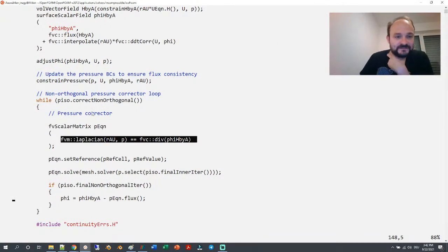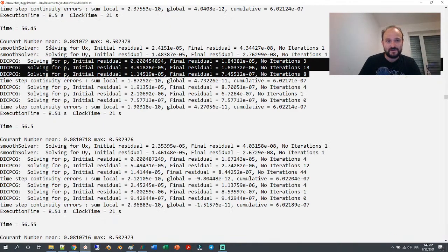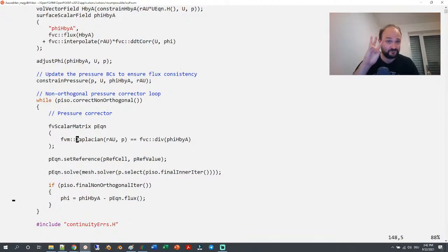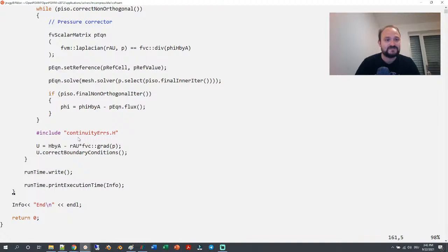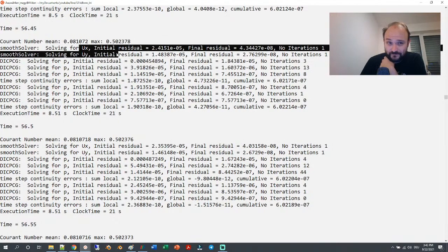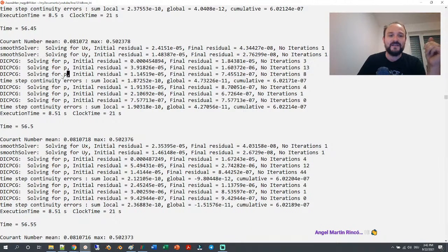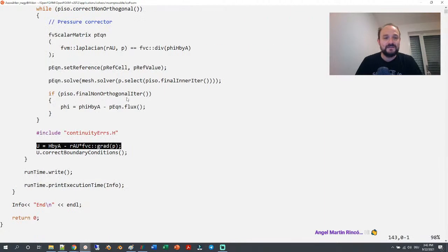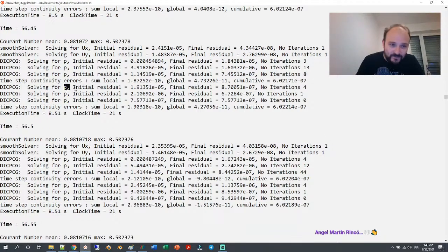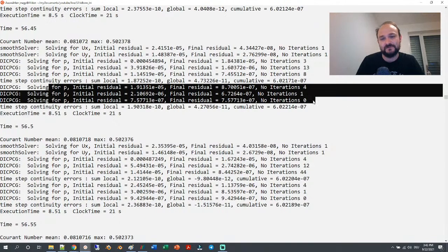But the difference is that we solve with the Navier-Stokes equations, then we solve these pressure equations 3 times, and then once we solve this, we calculate the velocity explicitly with the updated velocity. So we solve the Navier-Stokes equation, we have an updated velocity. Then we solve the pressure equation 3 times with this updated velocity. Then after the 3rd time, we explicitly calculate the velocity without solving any partial differential equations. And then we go with the updated velocity again 3 times into the pressure equation.